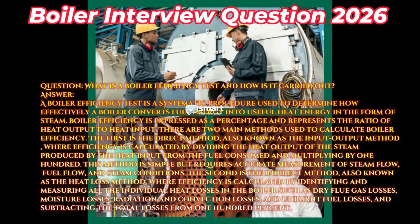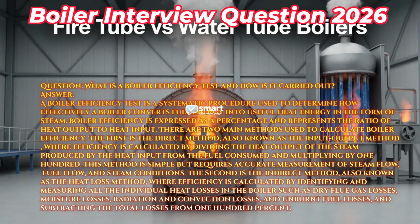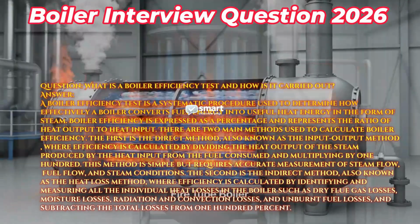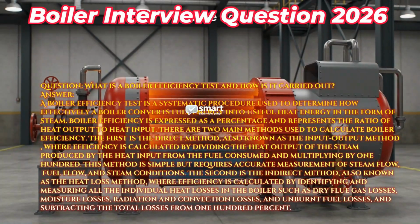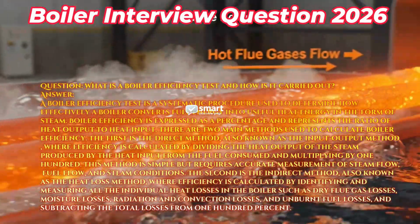There are two main methods used to calculate boiler efficiency. The first is the direct method, also known as the input-output method, where efficiency is calculated by dividing the heat output of the steam produced by the heat input from the fuel consumed and multiplying by 100. This method is simple but requires accurate measurement of steam flow, fuel flow, and steam conditions.